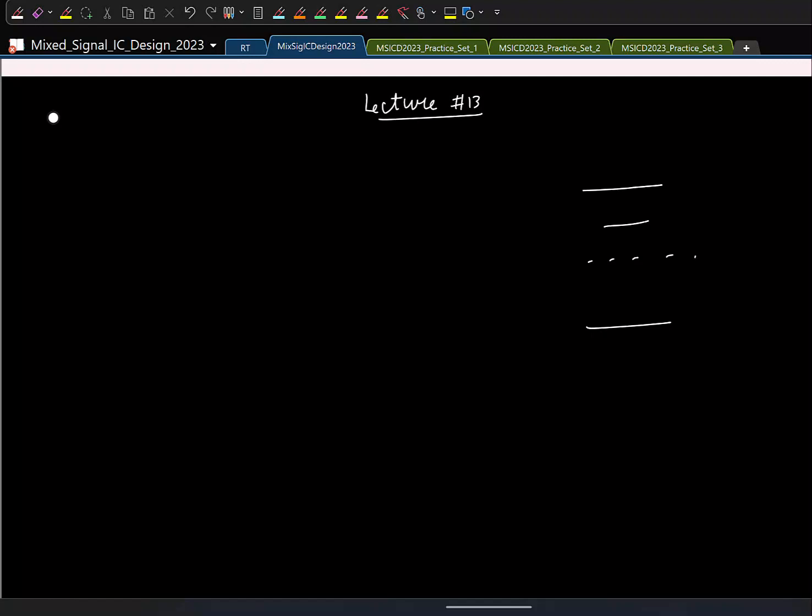So let's say we take a flash ADC, say it's a 4-bit flash. Say the final binary output you get is 1011 or something, and then you do this 2x interpolation. Let us say the decision from that is 0. Now we have to stitch all these together to form a 5-bit data, right?